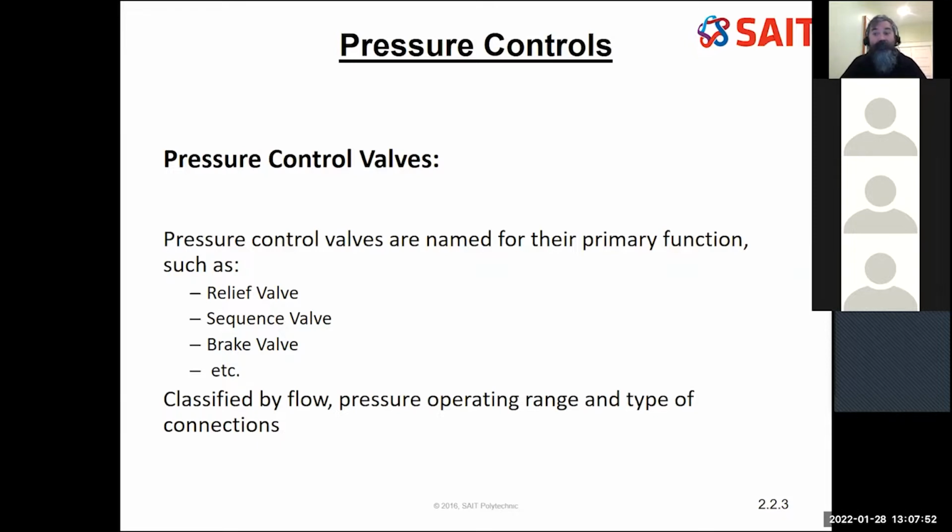And for some valves, you can use 2 or 3 different valves as a brake valve, absolutely. But depending on the pressure and how much control I want, I may choose a different valve to use. The drawing still just calls it a brake valve. I've got to look at the schematic a little bit more and maybe the parts list to understand exactly what we've got there. Now, all our valves are going to be classified based on certain numbers of things.